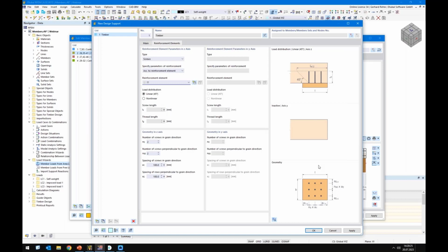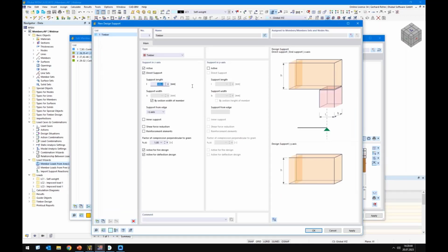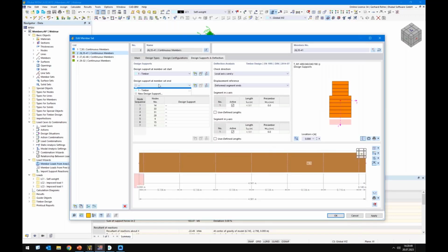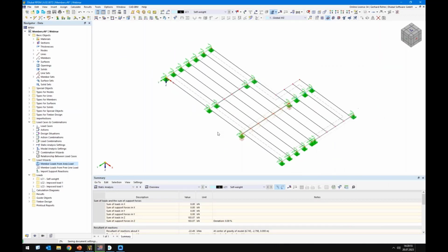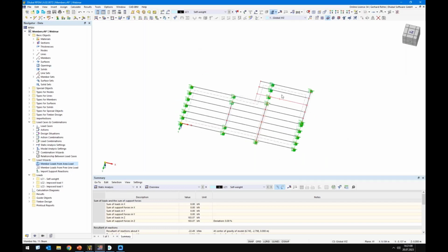Okay, and then the support pressure will be borne by the screws and not by contact via timber, where timber is actually really weak compared to parallel to the grain. Okay, I need to create it, of course. So 200 millimeters and 175, and also at the other side. Okay, that's it. We need to do the same for the cantilevers here.